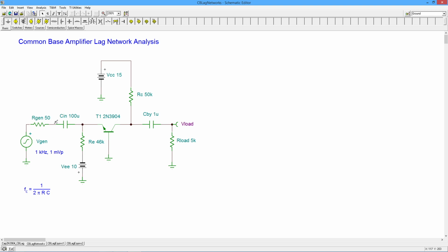We are going to lose some signal out here, though. And of course, you look at a 50 ohm and you think, well, what's to lose? It's only 50 ohms. But again, common base, low input impedance. In fact, the input into the emitter is just equal to R prime E. In other words, you got 129 ohms. So the Z into this thing is going to be 129 in parallel with this biasing resistor of 46K, which is basically 129 ohms, right?